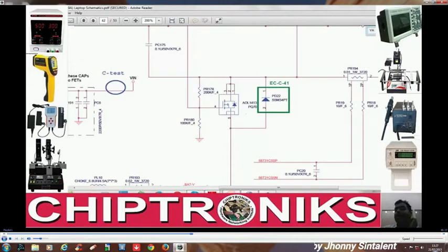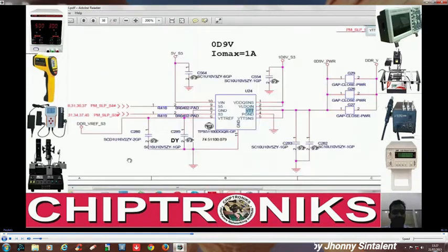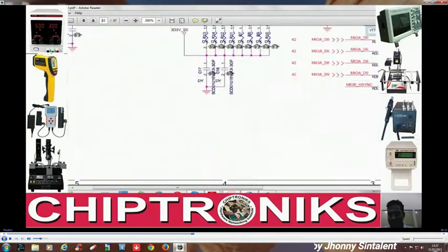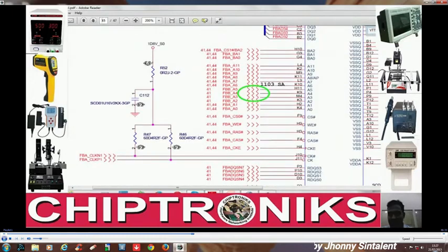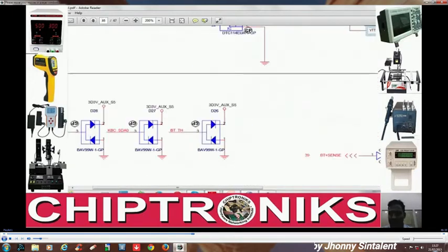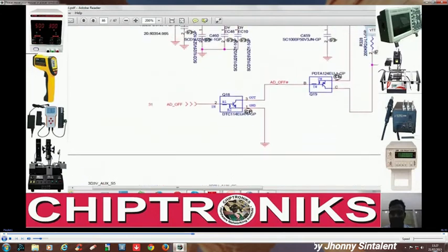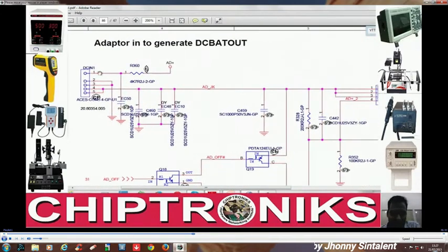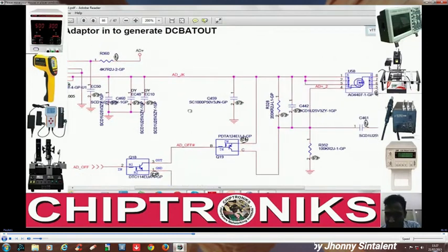And in the i3 board it is called V in, whereas in the dual core board it's called DC bat out, and we'll check the DC. This is the DV2000 board, and we'll look at the adapter section. Let's check the adapter section of the DV2000, and we'll correlate things, right? We always need to correlate things. Suppose the adapter is connected over here.